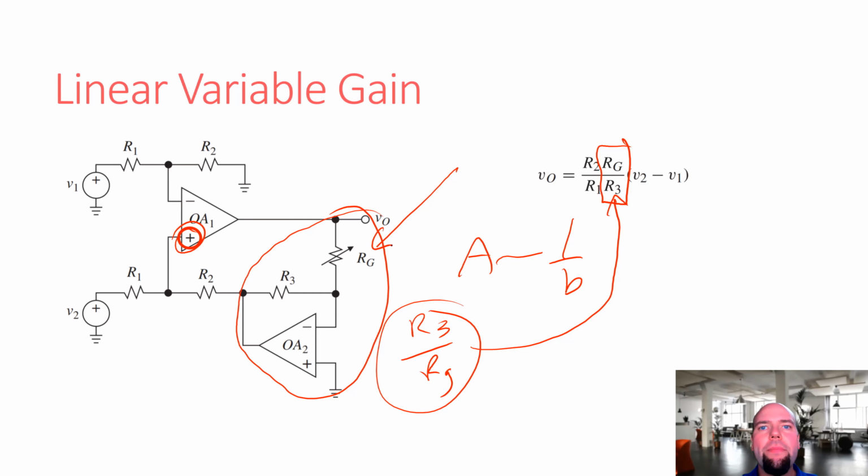And if we are feeding back on the negative of the feedback, we have to feed back to the other terminal. So we have to feed back to the positive. So basically, the bigger this output voltage gets now, the smaller this terminal voltage gets. So in order to correct an imbalance of the input, we actually have to feed it back to the positive terminal now to get proper stable operation.